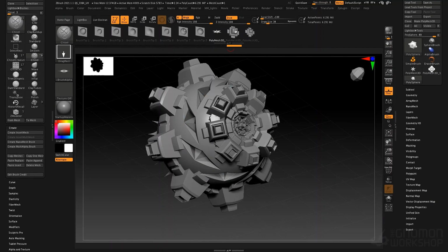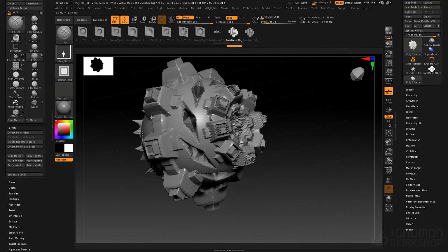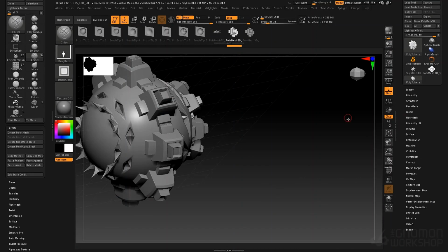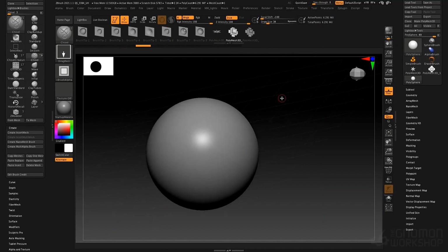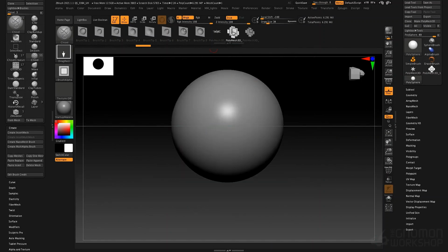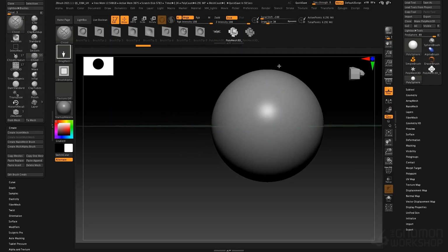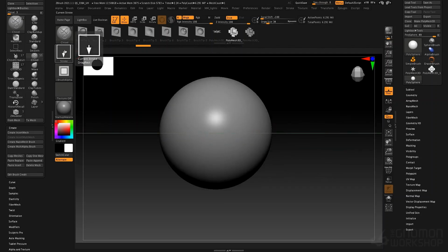Let's go back to our original mesh that we created without the beveling. And I'm going to undo back to our original surface. Now I'm going to use, you remember this particular version of the brush had the 90-degree angle drop off. So if I use this with the drag rectangle stroke on a chisel brush, it will turn off my radial symmetry.